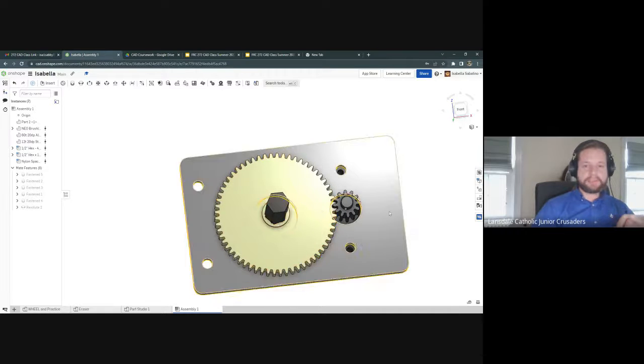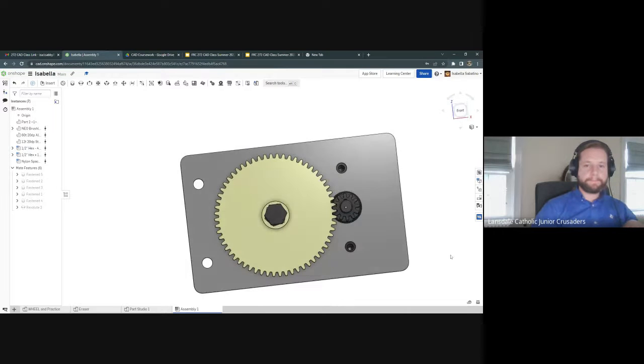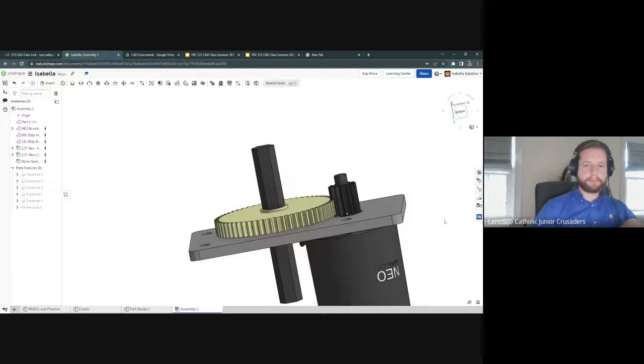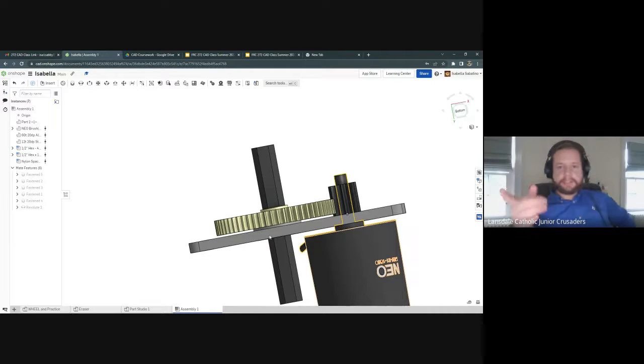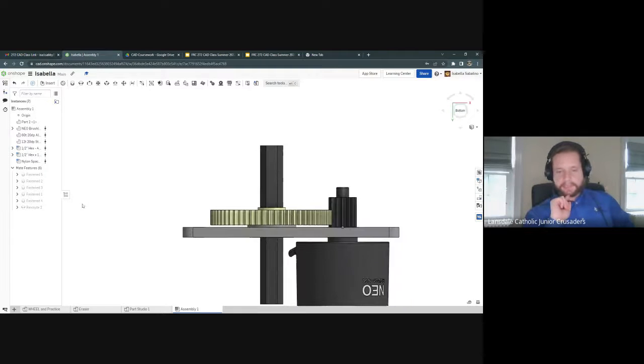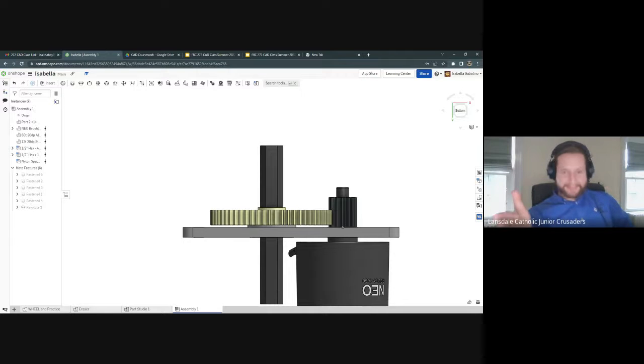Oh, you also did the same thing with your motor. Look at the space between the motor and the plate, look at the top or the bottom. Also, I'm going to give everybody a hint. Click the N key right now, Isabella. N as in Nancy. There you go, normal. N will always take you to normal, no matter where you rotate.